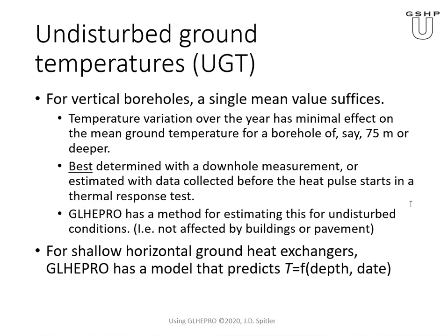meters. In terms of determining this, I think the best approach is a downhole measurement, where, sometime after you've done a thermal response test and all the drilling energy has subsided, you lower a thermocouple or other temperature sensor downhole and make measurements. We used to do it every 10 feet.